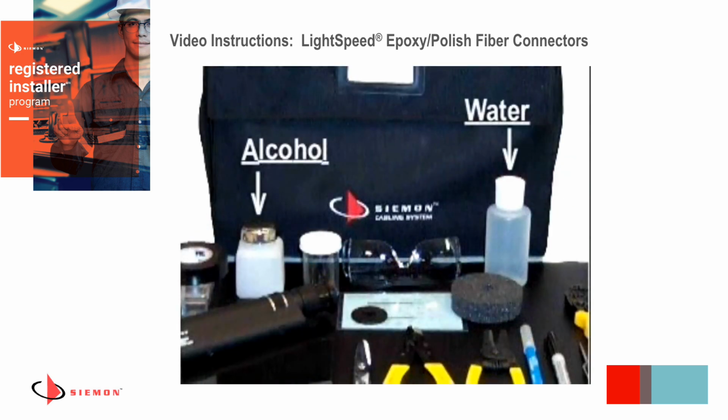Note that the F-Term L2 toolkit includes empty dispensers for the water and the alcohol. Apart from the limited supply of alcohol-soaked pads provided in the consumables kit, both dispensers will require filling prior to termination. The alcohol dispenser is provided empty because of federal shipping restrictions. For best results, it is highly recommended that 99% reagent-grade isopropyl alcohol and distilled or deionized water be used.